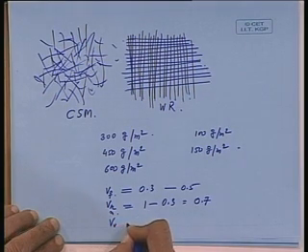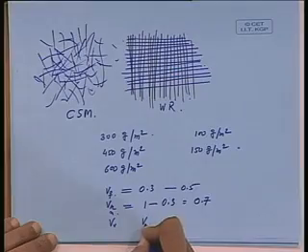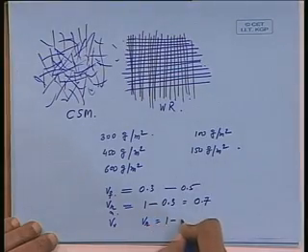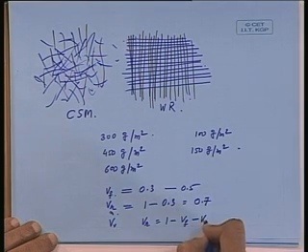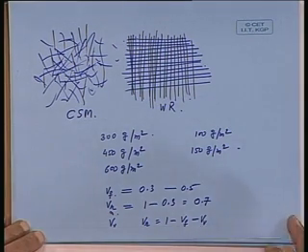Sometimes we say that volume fraction of vacuum. When you try to mold the thing, some bubbles are there. It occupies the volume, it is embedded inside, but it does not provide any weight or it does not provide any strength. So, if something is there, then we can say that volume fraction of resin is equal to 1 minus Vf minus volume fraction of vacuum. Usually the construction method should be such that volume fraction of the vacuum should be equal to 0.